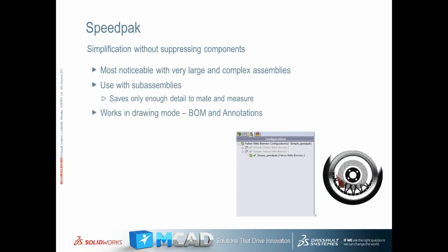SpeedPack. So what is SpeedPack going to do for you? Basically, it's a way to simplify your assemblies without suppressing components. These are going to be most noticeable in very large assemblies, very complex assemblies. But what it does is it takes out a lot of the data. It doesn't remove the graphical data.